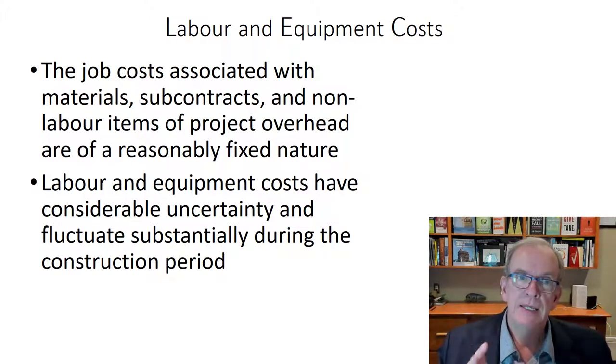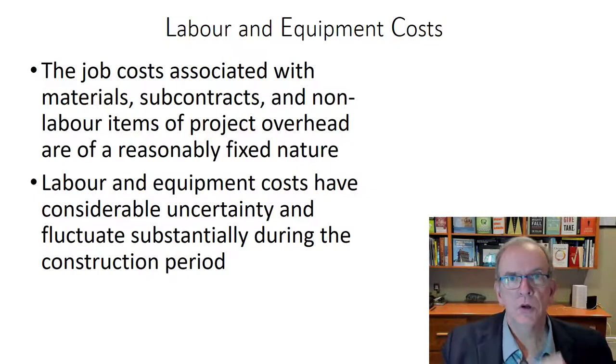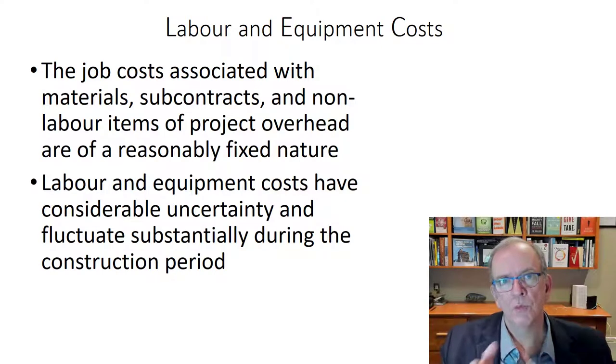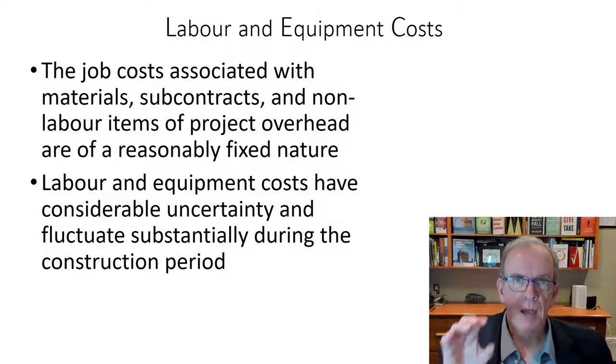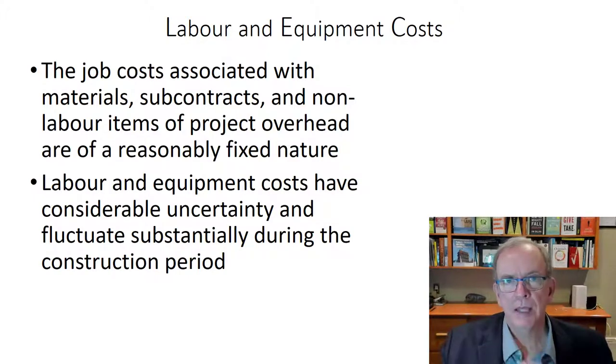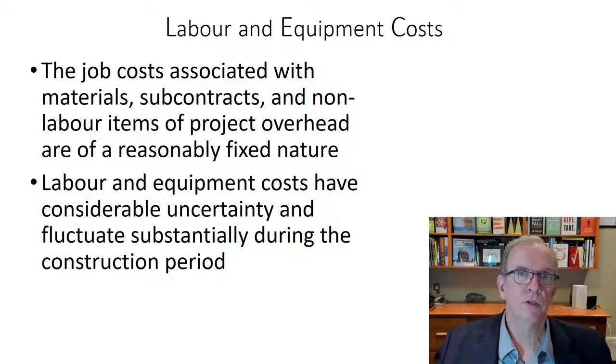Equipment is a variable cost, right? The longer the project takes using that equipment, the more the rental costs are associated with it. If it's labor, it's the same thing. I've got 5 people here, and we plan to allocate 5 people to be here 5 days. We allocated this backhoe or this bobcat to rent on this site for 5 days. Well, now if it's here 15 days, we're paying for another extra 10 days. We'd also have the variable cost of whoever the operator is, taking that much longer as well.